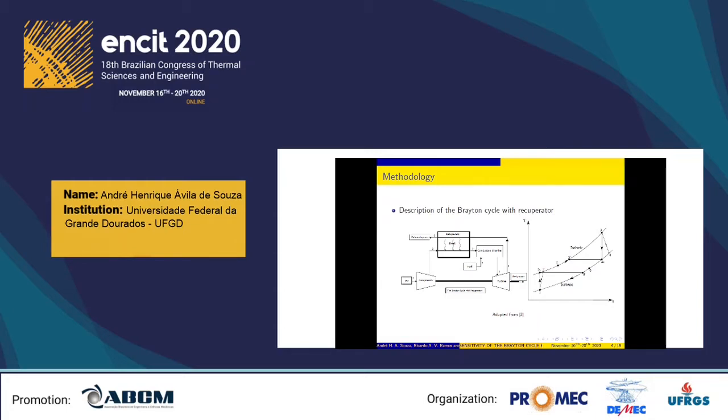The exhaust gases are cooled from state 4 to state 6, while the air leaving the compressor is heated from state 2 to state 5, before state 3, as presented in figure 2b. At the end, the exhaust gases leave the recuperator entering the atmosphere at a lower temperature than T4 and at atmospheric pressure.